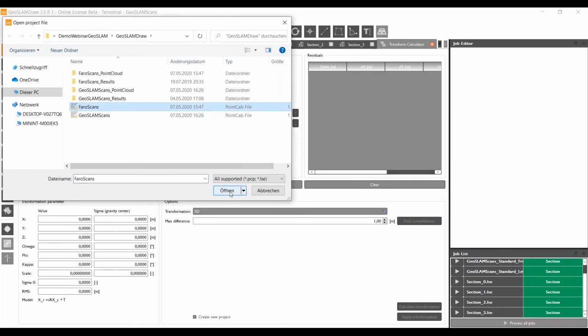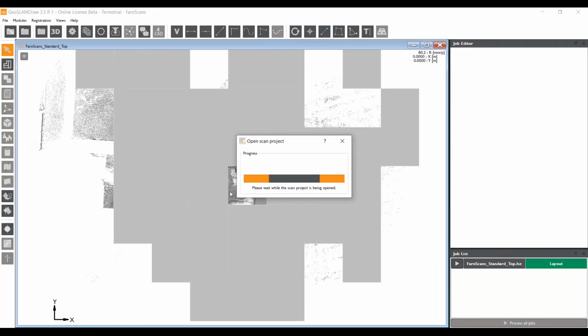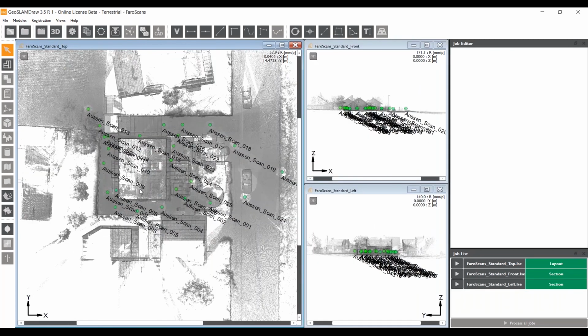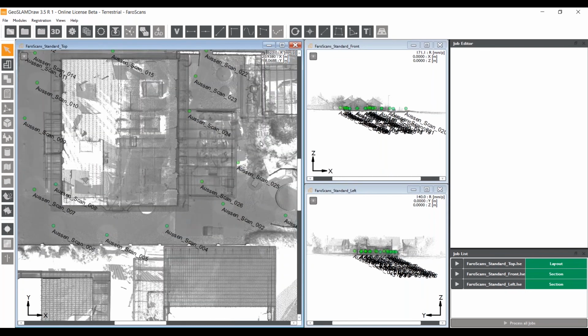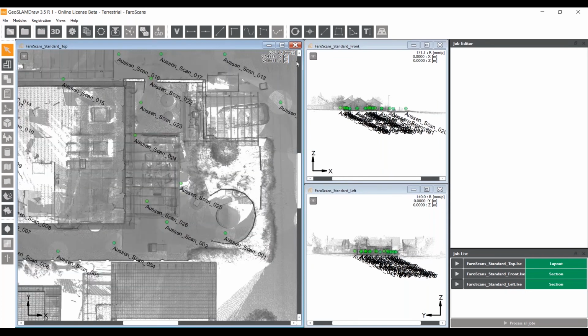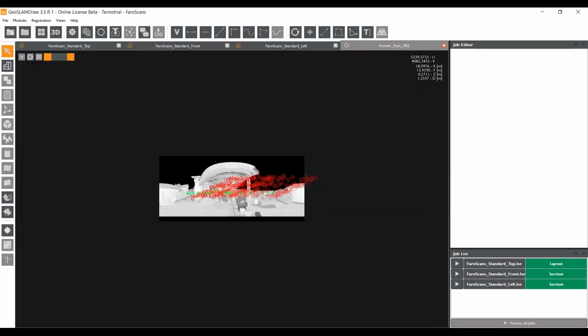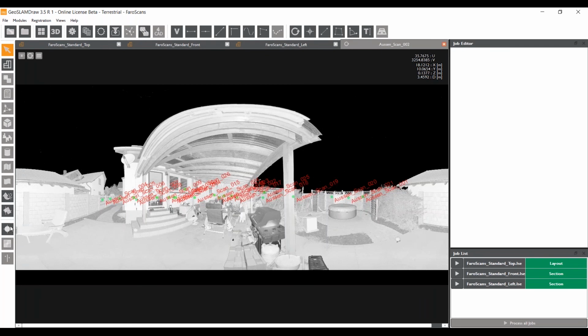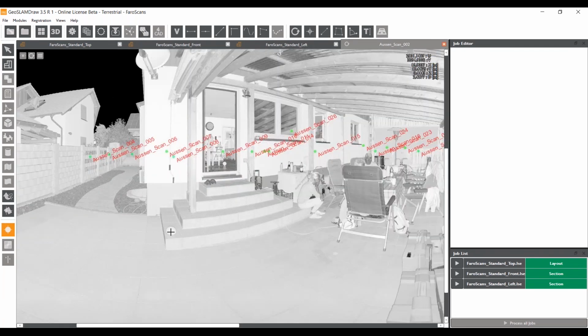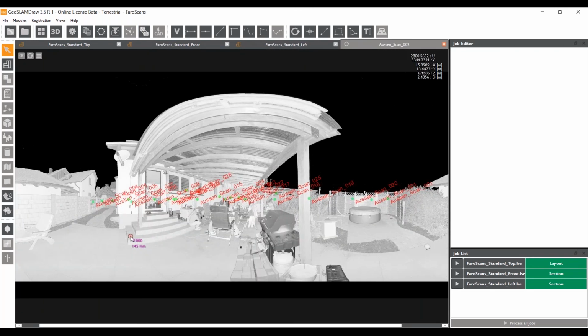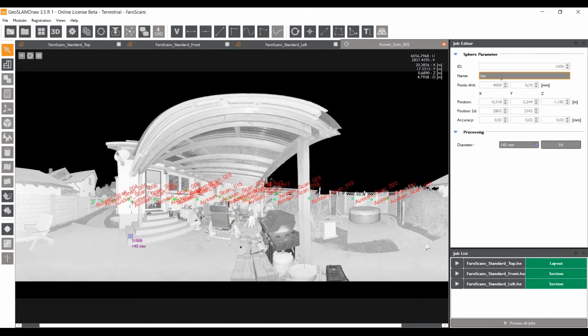and now we just open the Faro scans. So in the Faro scans, you see they are not georeferenced, and you have here everywhere the scan position where a green dot is. There was a scan set, and in this case, we just need to find the same spheres and mark them. So I open a panorama view because it's a lot easier to find them in there. Here we have our backdoor sphere. We can name that directly, so we have the correct name, backdoor.